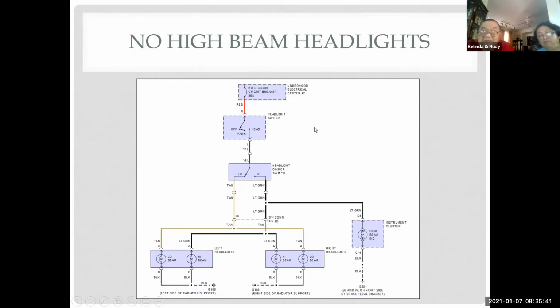The high beam filament is not working. There's a two filament bulb, high and then low. Right. So the high beam filaments aren't working. Are they not working because the filaments are bad? Or are they not working because the pin at the bulkhead connector is bad? Or are they not working because a rat chewed through the wire right here? We have a lot of rats in Fallbrook.